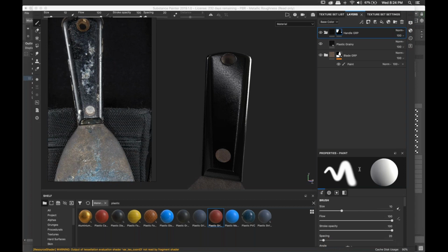How are you marking selected or selecting individual parts again? Yes, I'm using the polygon fill, so Peter is correct. It's the fourth tool down, and then if you switch to UV mode, you can just marquee, and it's just converting your selection to the UV shell.